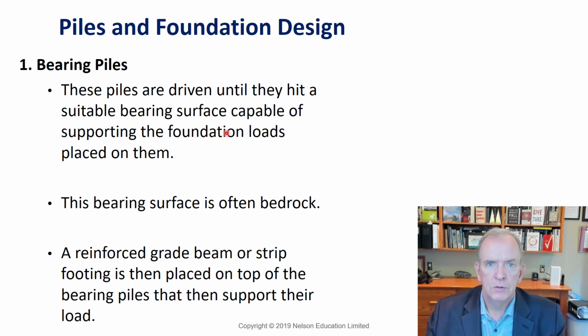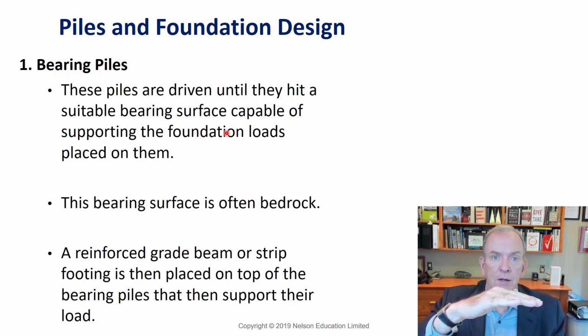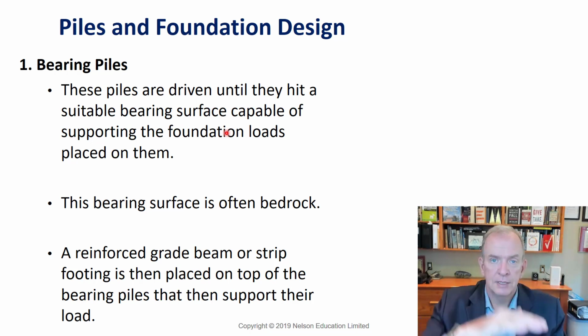You see it very commonly used in large buildings, but sometimes you see it on houses as well, where there's an issue with support. And certain climates you might find that you need bearing piles in a lot of locations. I know in the area of Winnipeg, the soil is very unsteady, and it tends to heave a lot and move a lot. So even for a concrete slab in a community center, there might be a number of piles that would be driven into the ground to support the slab and to ensure that it doesn't move. And in fact, the slab is usually suspended off the ground because it's more concerned with the heaving of the soil than the settling of the soil.